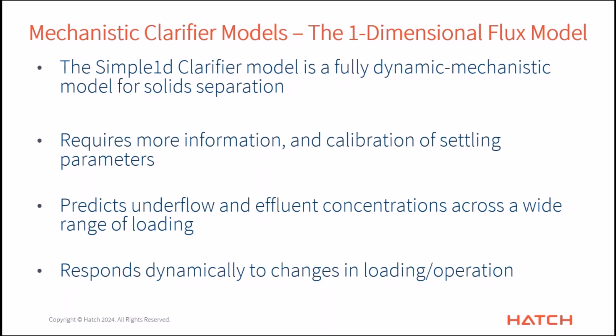Now it does require more information to use this. You need to specify a lot of the physical details. What is the surface area? What is the depth? And also calibrate the settling parameters. I'm going to talk about that a little bit down the road here. But basically, it predicts underflow and overflow concentrations, in fact a concentration for all 10 layers in your model. And it is also a fully dynamic model.